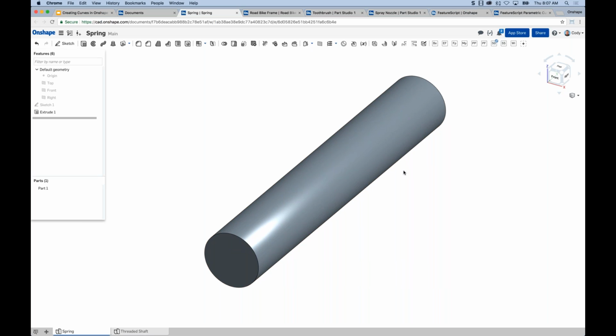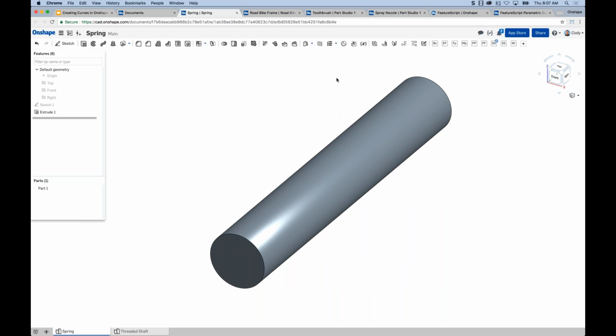Now, this is just one technique, but it's a common one in applications like this, because all I need to do now is select the helix command from the toolbar and then left click the actual face of the construction cylinder. Here you can see it automatically grabs the diameter, and then I just have to define how many revolutions I want and what the start angle is, so to speak. Just keep in mind, this is just one technique. I'll show you another one in just a bit. But it's an easy way to define both the length of the spring or thread and the diameter of it.